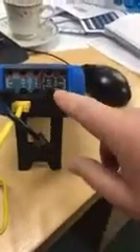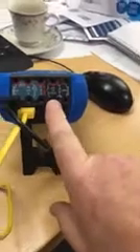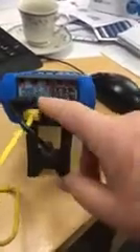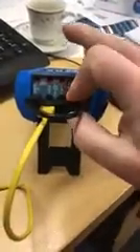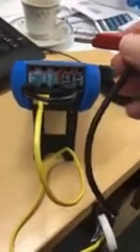The power supply is isolated, so we do a common from the 24 volt negative to the measure negative. Now note how one section is light grey and is source, the other section is dark grey and is measure. So if we go in there, and then coming from the transmitter, we've got our power, which we're going to measure the current on.